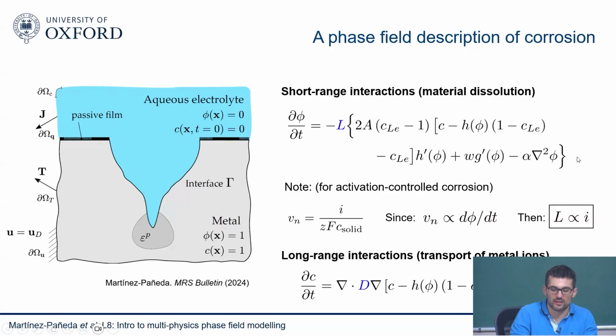And what this means in practical terms is that if you have 1D data, which we all normally do, of corrosion of a given material, you can do a 1D virtual experiment, and you can define the ratio between L and the corrosion current density. Then for any other corrosion current density in that material-environmental system, you know what your L is. So it's not ideal.